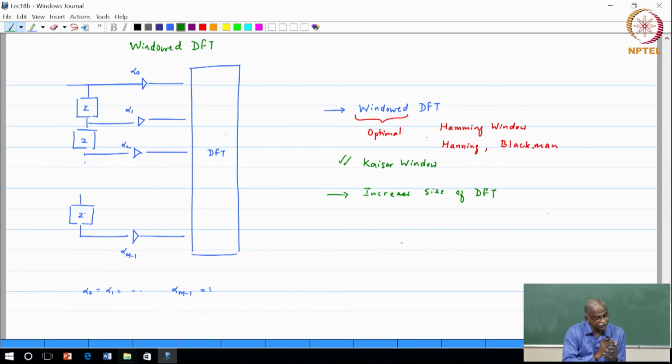The limitation is that it is a non-stationary signal, because the signal has got time varying characteristics. Let us say a burst of tone appears for a period of time. If you take a very large window, you will lose that information. So, you may not be able to have the luxury of increasing the DFT size. So, sometimes this may be a problem.